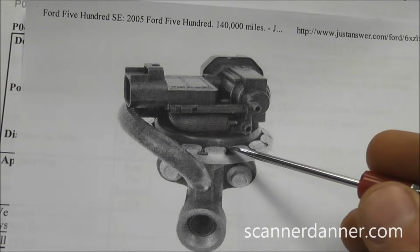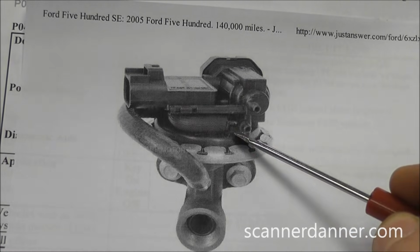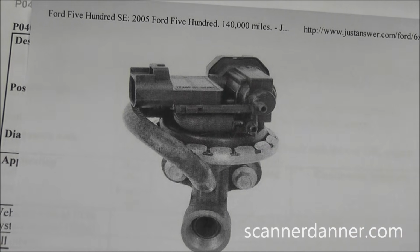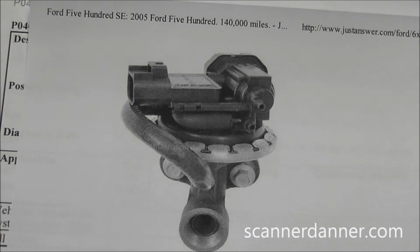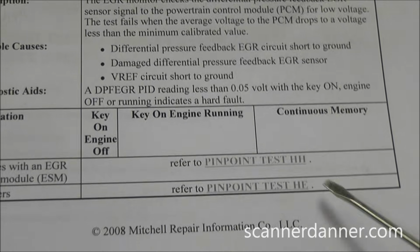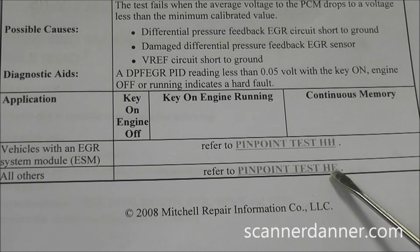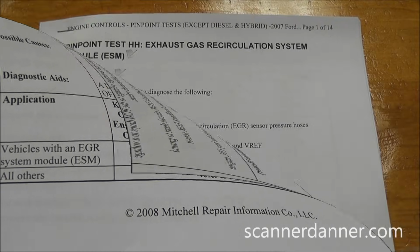It is not this one. I've already done it. It's the single vacuum hose going to the EGR. It's the older design, even though this is a 2007. It's not this one. So our pinpoint test that we're going to follow is HE. If you were following a manufacturer flowchart, it would be this one. So I wanted to inform you guys on how we did that.